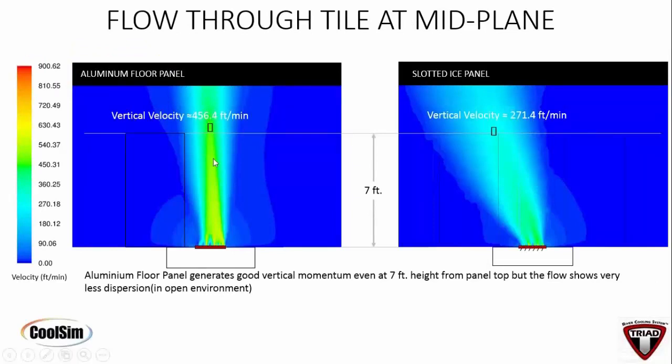Over here on the left, this is the 56%er, and it's going straight up into the ceiling. Now, what you want is some air to penetrate this boundary, this cabinet boundary, like over in this shot. This is the ice panel. What happens here is as that air comes up and bangs into that panel, it creates turbulence, and that turbulence causes the convective heat to transfer. So you want some intersection of the cool air coming out of the floor with this area.